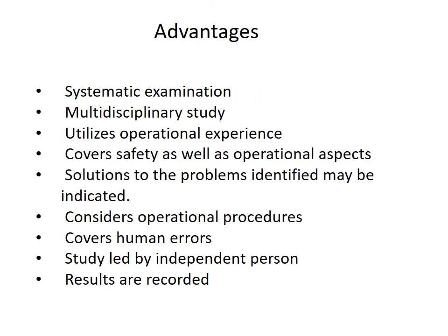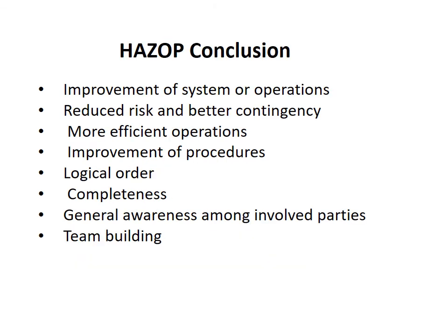Advantages of HAZOP. It gives systematic examination, multidisciplinary study. It utilizes operational experience. It covers safety as well as operational aspects. It gives the solution to the problems identified may be indicated. Considers operational procedures. Covers human errors. Study led by independent person. Results are recorded. Thus we can conclude that HAZOP leads to improvement of system or operations. It reduces risk and gives better contingency. It gives more efficient operations, improvement of procedures, logical order, completeness, general awareness among involved parties, and team building.